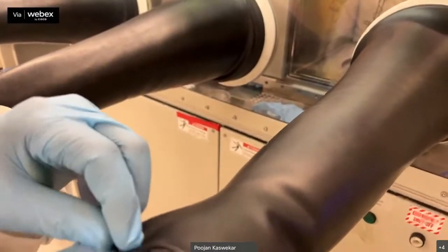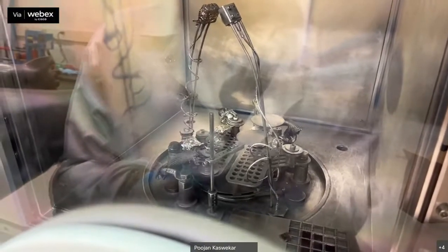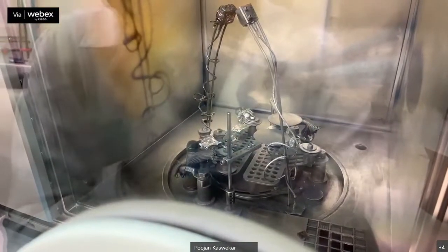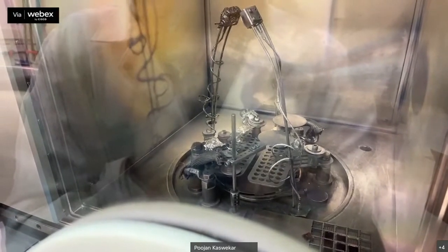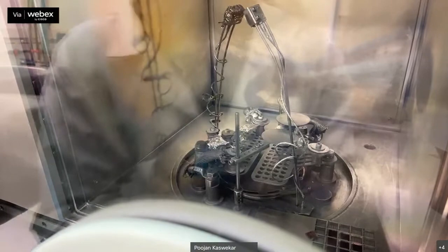Actually, yesterday we fabricated these solar cells, and today we are going to discuss how to characterize them once you have fabricated these devices and how they look. Good morning, everyone. Yesterday we left off when we deposited rhodamine on top of PCBM. One step remaining is the evaporation of silver. Today we will do both processes simultaneously: we will show you the characterization using IV as well as the deposition of silver.